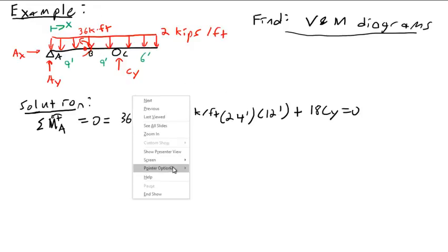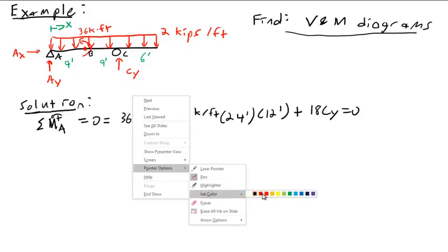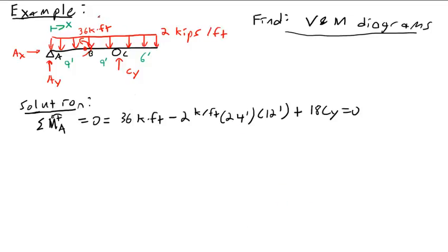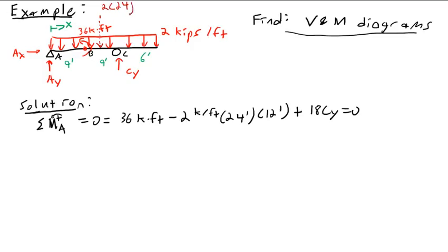So in other words, we're replacing this with a 2 times 24 point load at a distance halfway across the beam. We're replacing it with an equivalent point load, only for the sake of finding reactions.